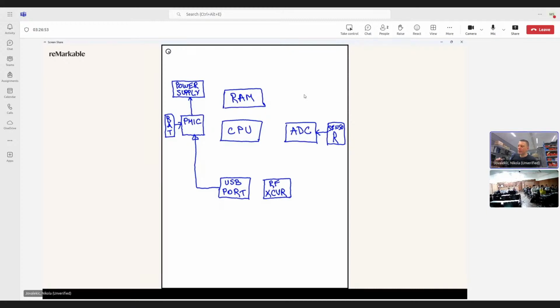What kind of interface would you be looking for if you want to connect this transceiver to the CPU? What kind of bus would you use here? Differential bus. Why would you use a differential bus? Because of the noise. Okay, I understand your point. Yes, differential signaling, or differential ended signals, are more immune to external noise because, in the ideal case, it will be cancelled.